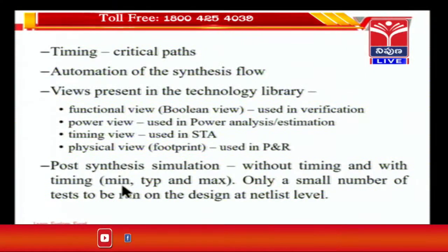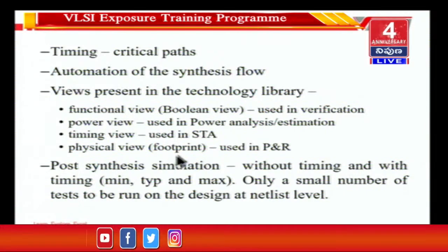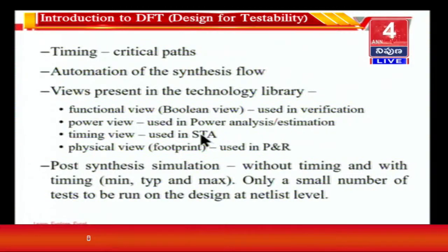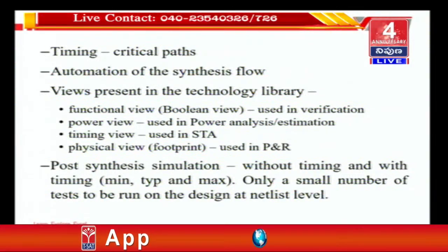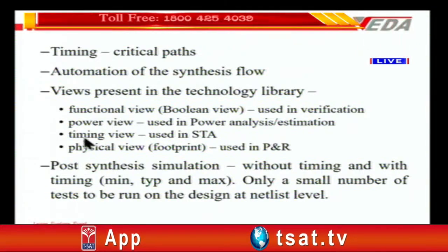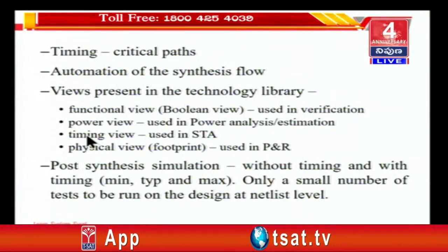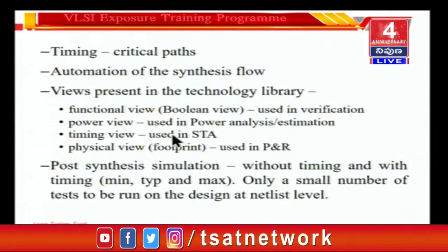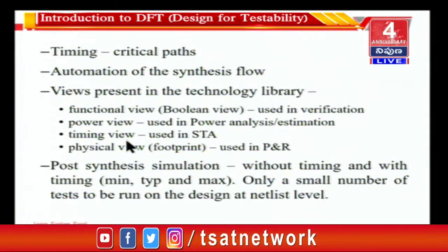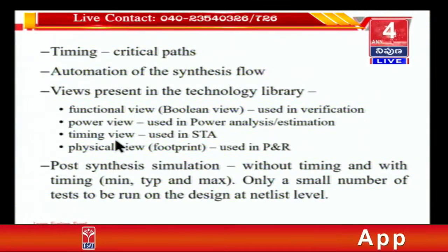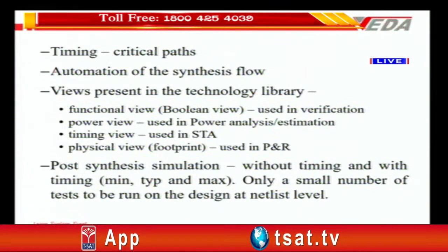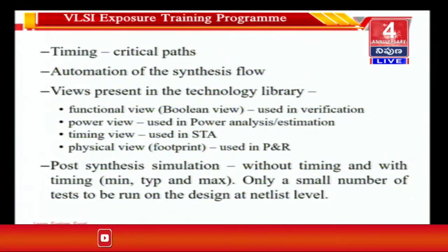So the timing view is quite extensive, and this information is made use of by the static timing analysis tool. Static timing analysis is a tool that can be used at different stages of the manufacturing flow. It can be used in the gate level simulation to find out how many paths are there, because the static timing analysis tool does not apply any test patterns to the circuit. It only reads in a circuit, and based on the connectivity information in the circuit, it will know what the paths in the circuit are.